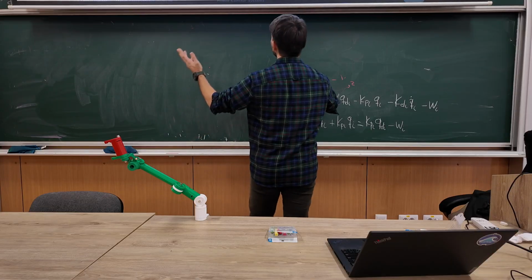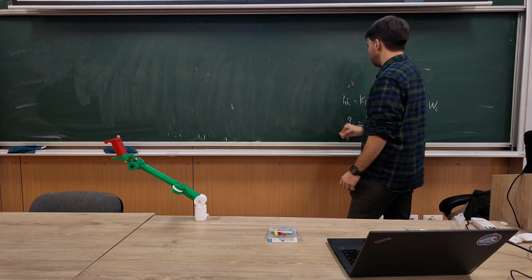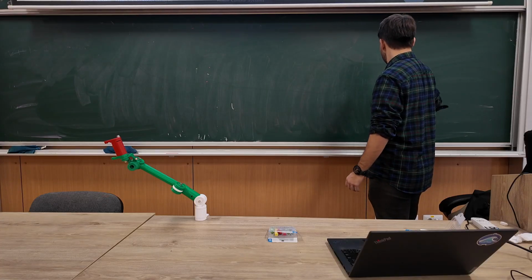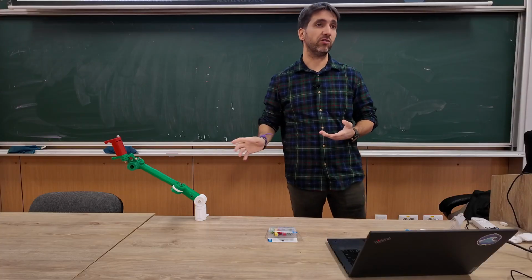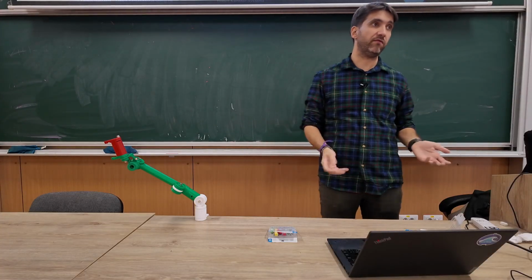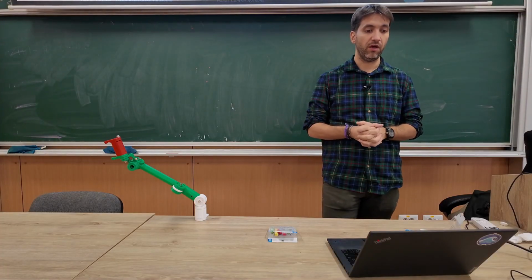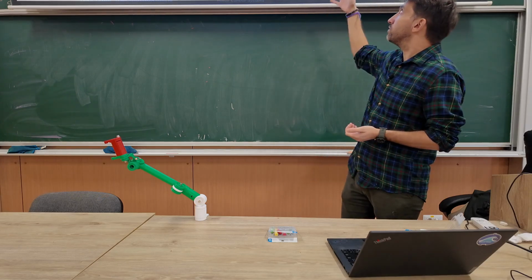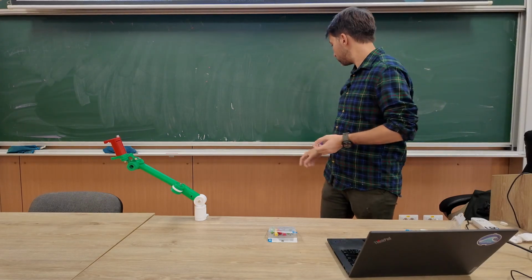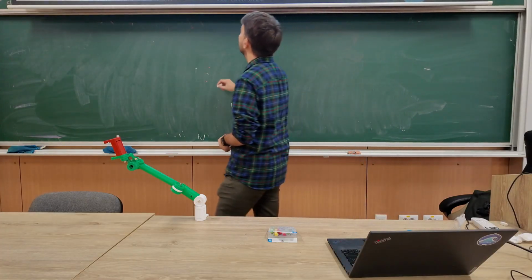Okay, so starting from the model, we said that if I want to design independent joint control, I choose my torques to have some values following the PD controller, PID, or whatever controller I want to implement. I can do this for the whole vector of torques, right? So starting from this one, my torque,